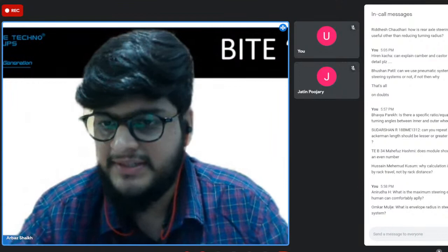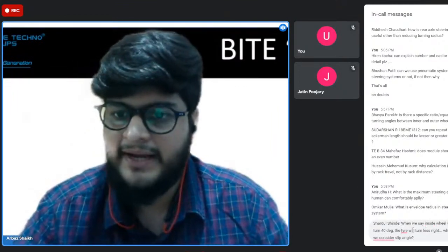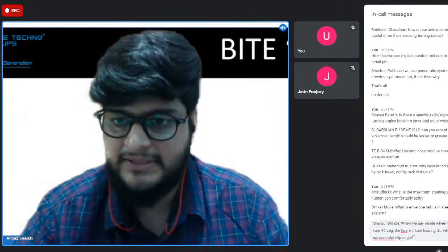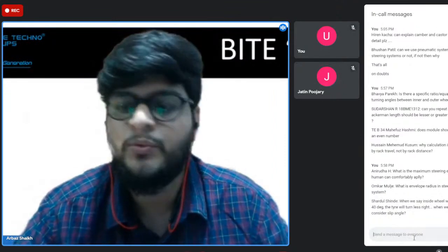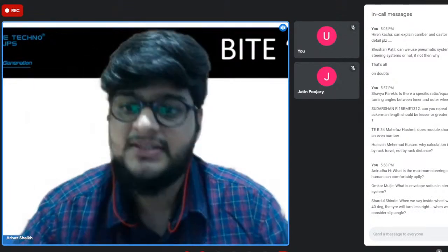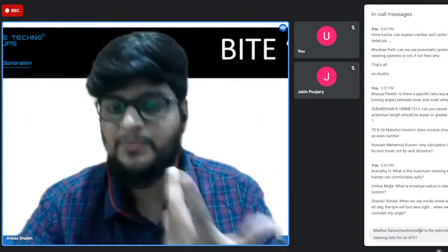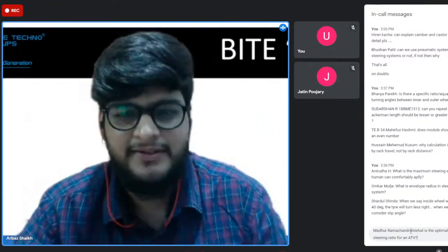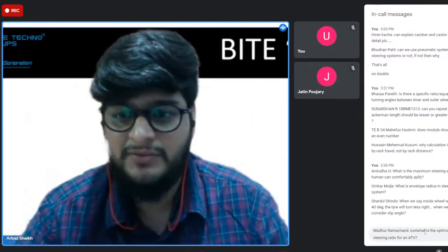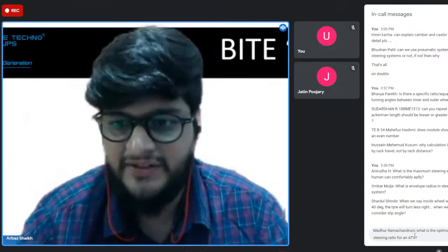Hussein is asking why calculation is done by rack travel and not by rack distance. What do you mean by rack distance? Can you please explain what it is? I am not getting what rack distance actually is. Okay, Anirudh is asking a very good question. What is the maximum steering effort a human can apply, right? If you're punching someone, it's around 200 Newton, even more if it's a professional fighter. But if you're trying to turn your steering wheel, somewhere around 50 to 75 Newton.